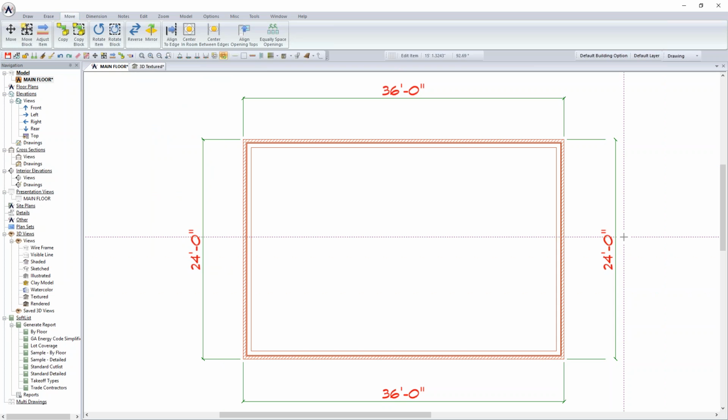A command that you will use a lot within SoftPlan is called the cleanup feature. Now what the cleanup does, for all intents and purposes, and it's kind of a throwback, the fact that we have a drafting brush for an icon. But what it does is it doesn't just sweep the eraser bits off the vellum, it actually goes through and calculates the entire drawing.